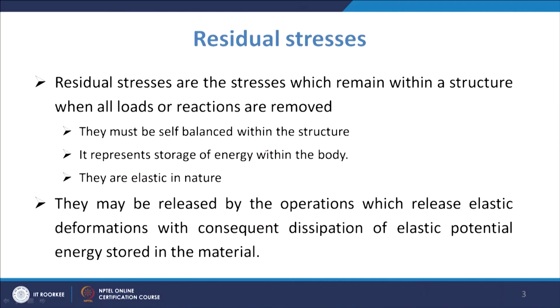So, coming to the residual stresses. Basically, residual stresses are the stresses which remain within a structure when all loads or reactions are removed. The forces are balanced within the body; they must be self-balanced within the structure.